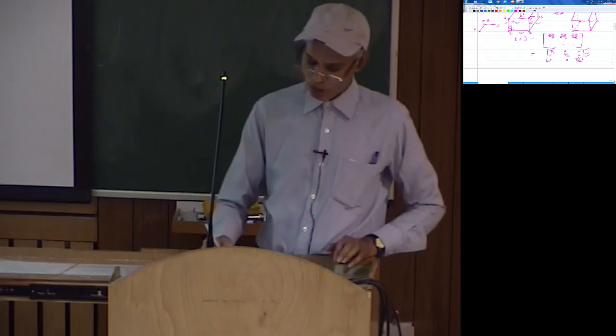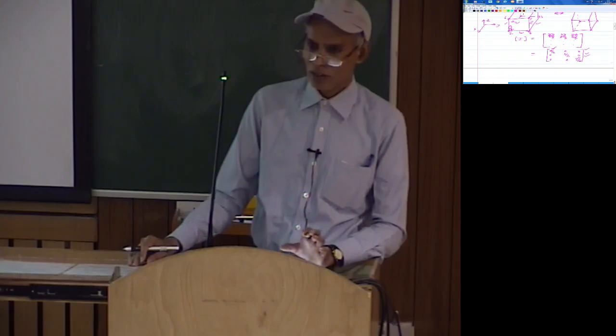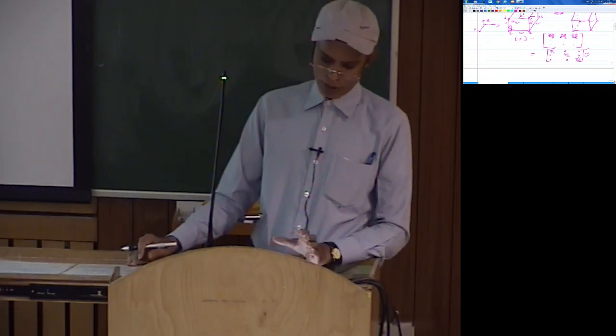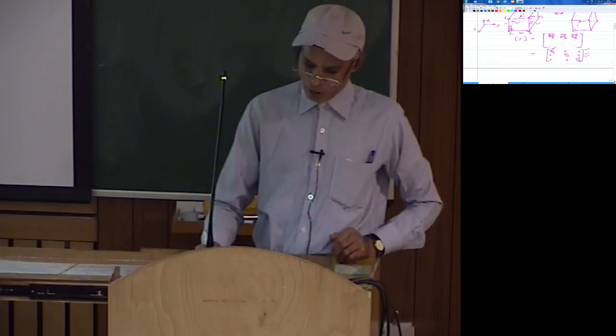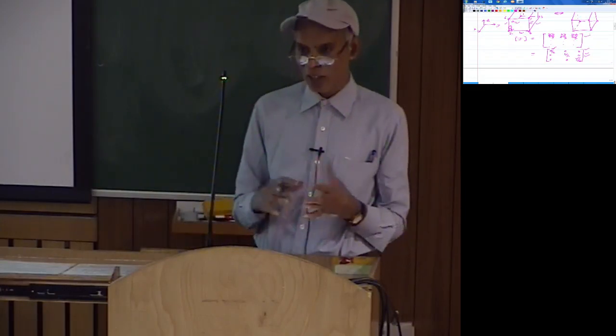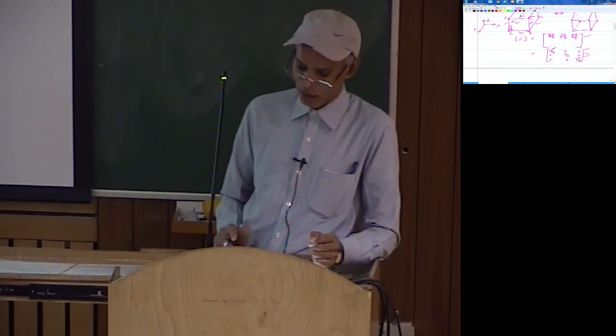So then what will happen is, you see the Jacobian matrix is going to be a function of xi and eta. And when the Jacobian is a function of xi and eta, depending on these angles, the dependence of this Jacobian on xi and eta can be quite complex. The powers of xi and eta can go to higher numbers.